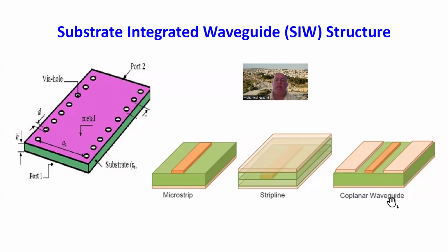And then we have the coplanar waveguide, which is basically a microstrip line that has two adjacent ground channels. So whenever we use this, we have to eventually transition to one of these. And all of these will require us to do a transition from substrate integrated waveguide to a microstrip line.